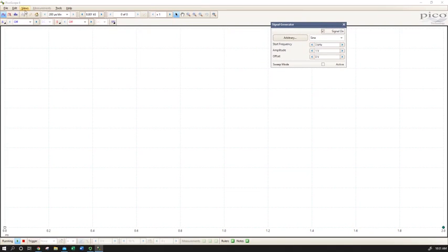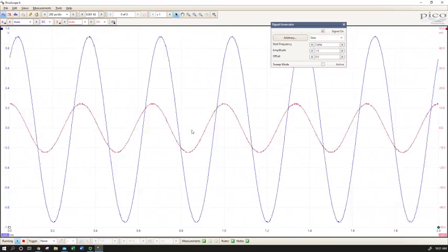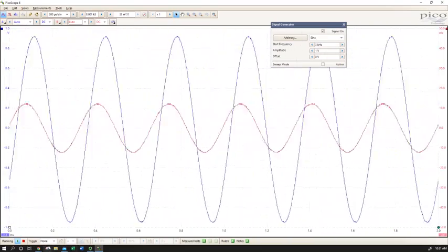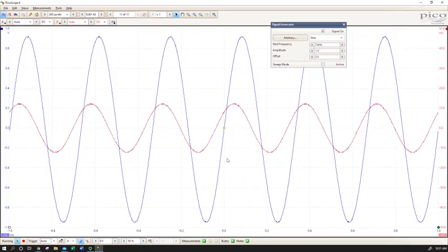We're running. Why are we not seeing anything? We didn't turn our channels on. Let's ask our oscilloscope to look for something. Let's give it a trigger so that it stops. Okay, we're definitely not at resonance of 3 kilohertz because we've got a very clear phase shift. So again, our resistor is leading our full circuit.